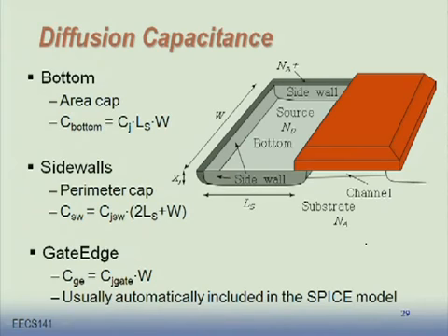Do we know how to calculate the diode capacitance? What is it equal to? What is it proportional to? The area, that's pretty good. What else? How about the voltage proportionality? Is it linear? It's a square root in the simplest model that we have learned. And if somebody has tortured you with this gradient of doping, you'll find out it's a cubic root. In practice, it's going to be something between the square root and the cubic root, and the bottom line is it's nonlinear.